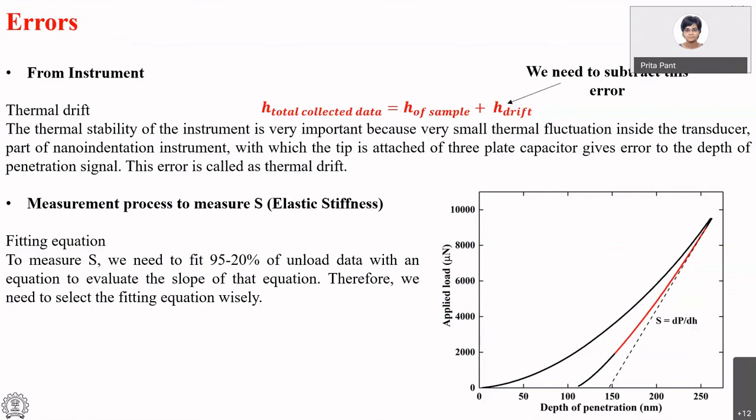Drift due to doing these experiments at, let's say, 23 degrees at which you are maintaining your lab. So the depth that we measure is depth of penetration into the sample plus movement of the tip due to thermal drift.